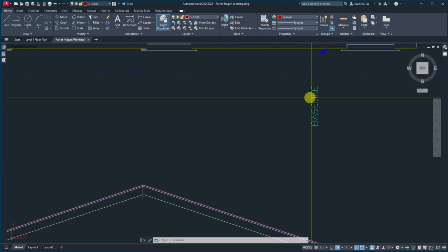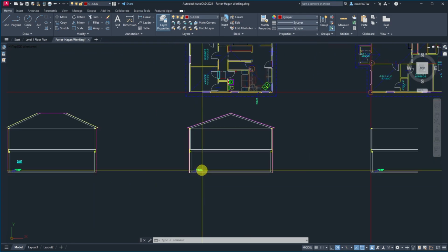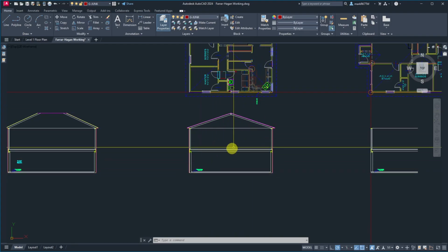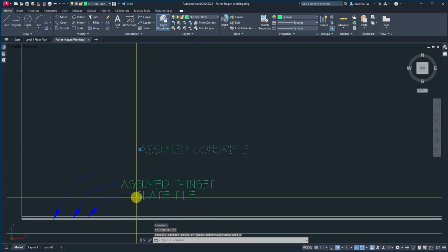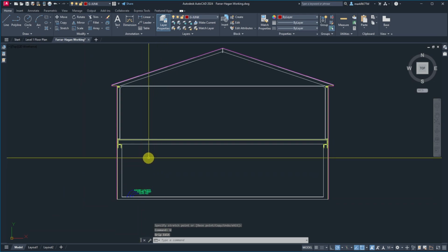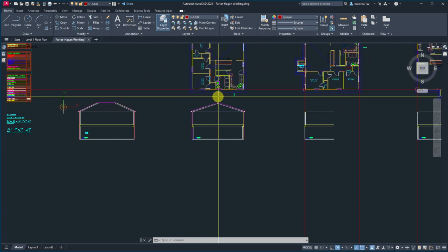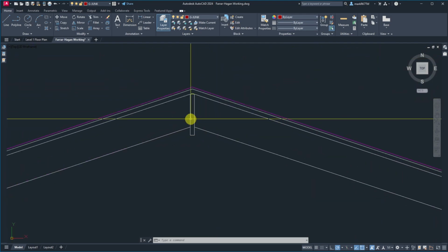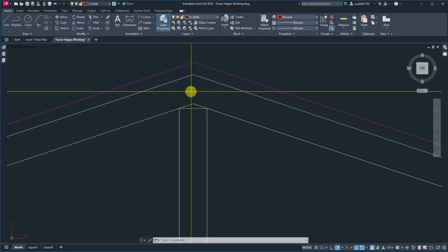So this baseline is the wrong text even to use on it. This is the wrong text to use on it. Oh, no, that's the right text size. See how it's smaller. It's 1/2 the size. But these became unassociated to their leader. So I'll show you how to fix that. But it depends on how your blocks are set up too. So now that we have that where it's supposed to be, then I can start to transfer this information across.